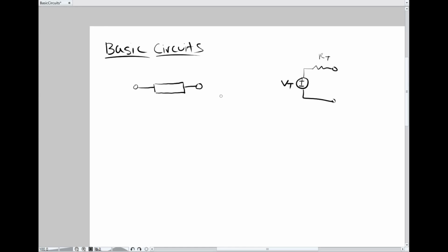So a circuit element is just some arbitrary thing. We haven't really described what that could be yet. For the purposes of this lecture, I'm going to pretend that circuit elements have two terminals. However, we have symbols for circuit elements that sometimes contain three terminals. And it's described by two measurable physical quantities. One of them is called voltage. The other is called current.